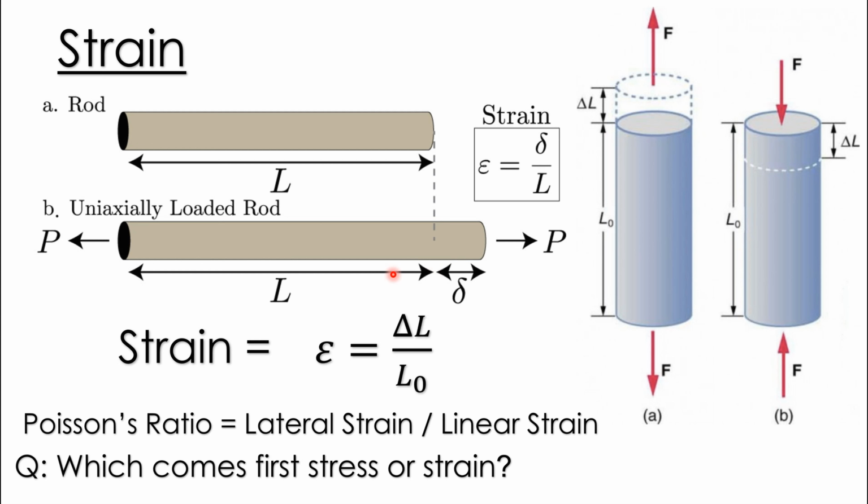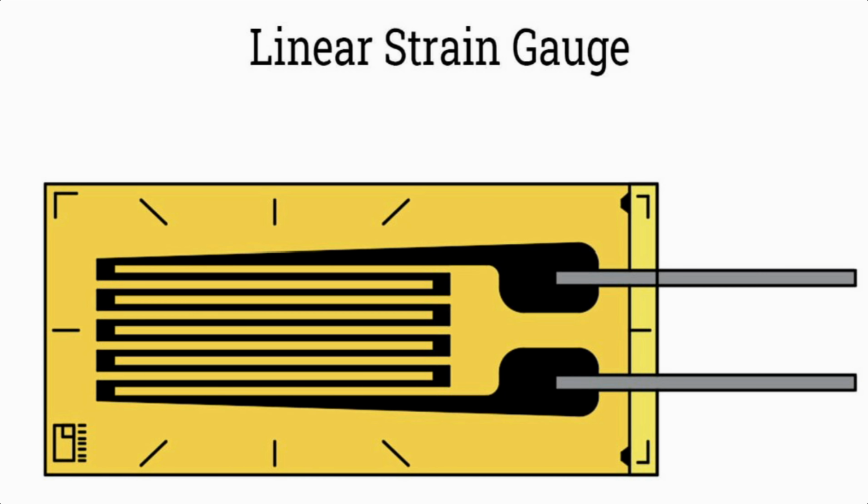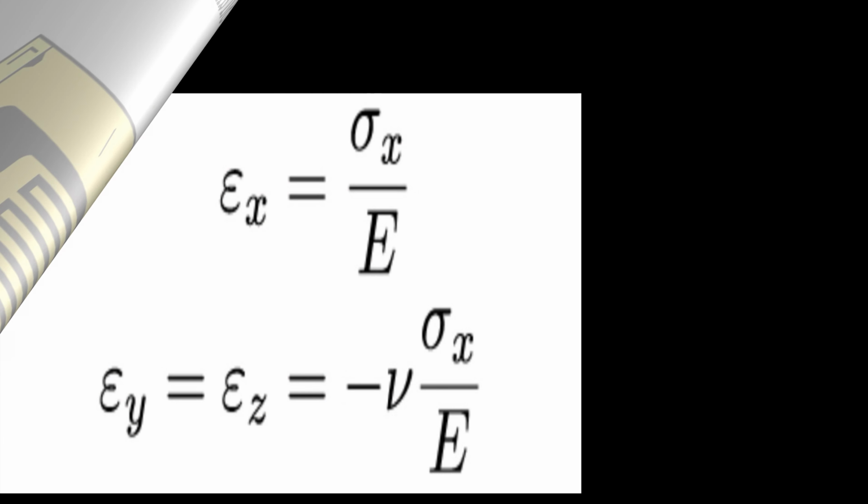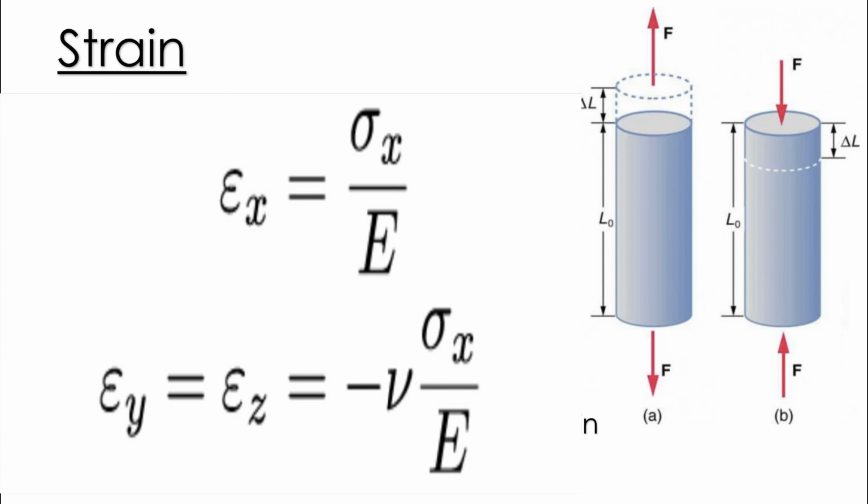As we explained earlier, we cannot measure stress directly, but we can measure the strain through strain gauges. The amount of deformation in a body or an object we can measure easily. After measuring strain, we can calculate the stresses in a body or an object through the stress-strain relationship.